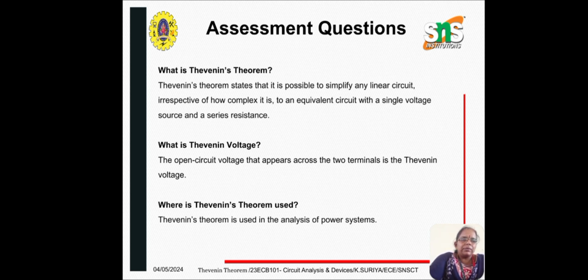Next one is, what is Thevenin's voltage? So the open circuit voltage that appears across the two terminals is the Thevenin's voltage. Where is Thevenin's theorem used? It is used in the analysis of power systems.